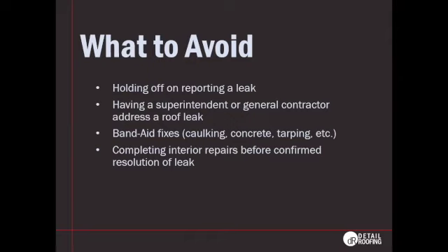Band-aid fixes like caulking, concrete, or tarping can work in an emergency situation where you're trying to mitigate any further water ingress immediately. However, for the long term, these are not recommended. They're not permanent repairs. Concrete is not compatible with the membrane systems. And tarping, again, is just a quick fix, not something that you would want to keep in place for a long period of time.